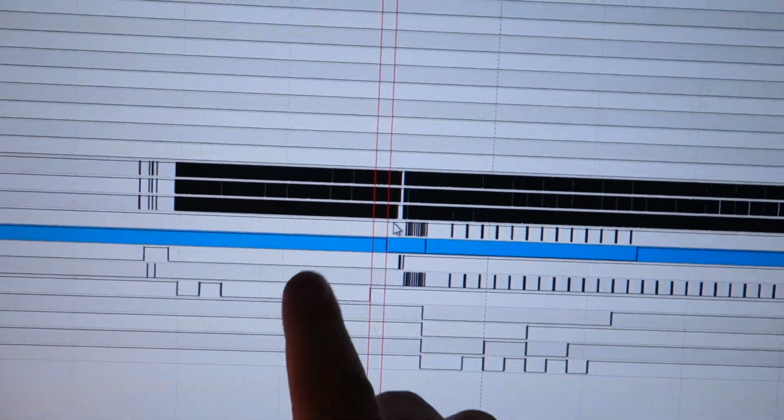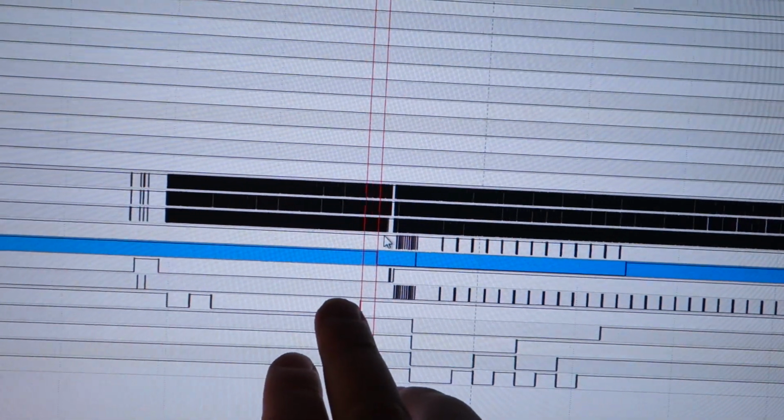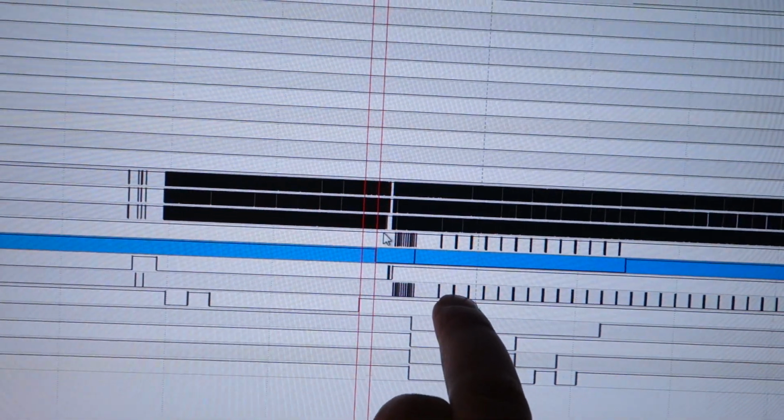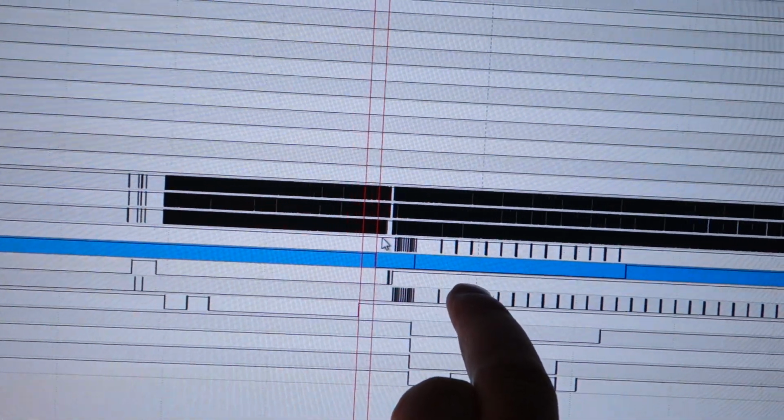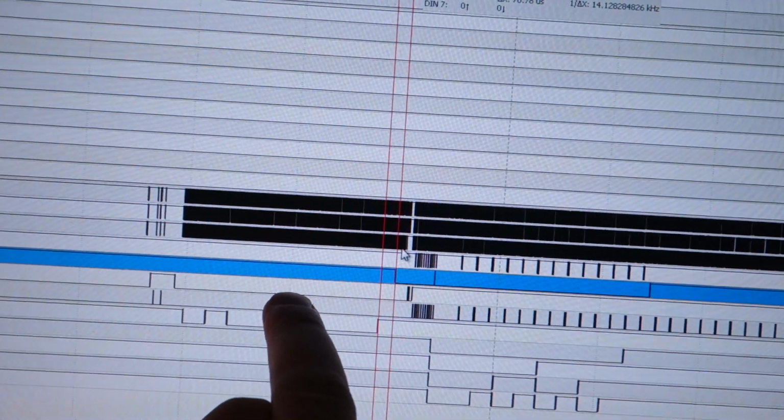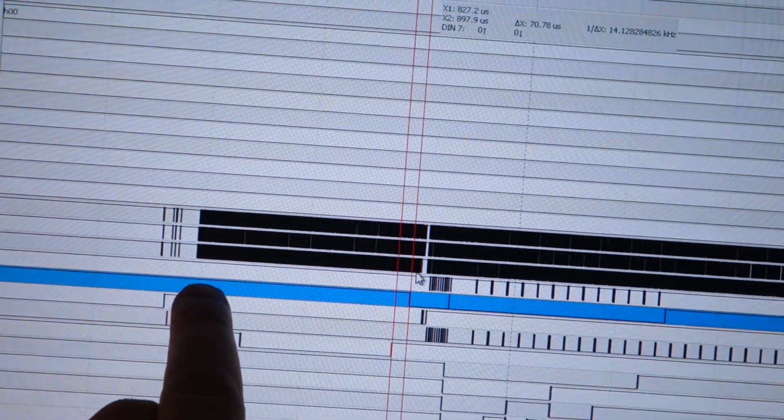So what it does, it opens up. I have 3 inputs there. This is the read line. This is the chip select. If this one is low, then it's RAM. It wants to load from RAM, like here. You can see these two come together, but this one is high, therefore there's nothing coming out.